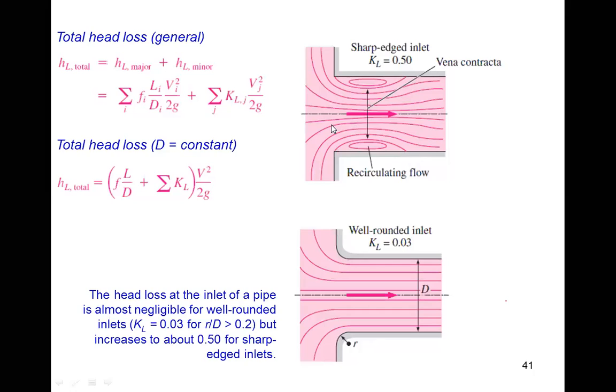So what you have to do is put on the brake and slow down a lot, and then you can take the turn, right? So the energy that was available is getting destroyed or wasted. Wherever you have a sharp change, the same thing happens in the case of fluid also. Here you have a sharp change, so a lot of energy will be lost.